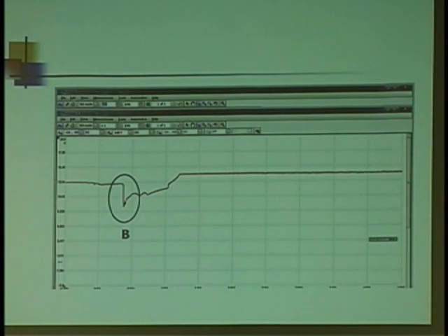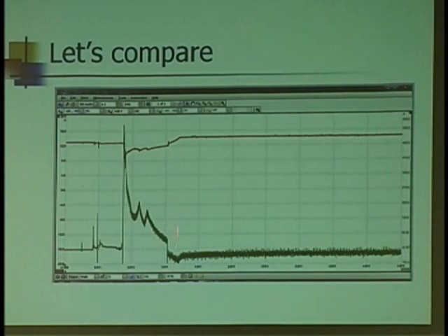Now on a VAT 40, you generally cranked about 200 amps or so. My starter just pulled about 500 or 600. Wow. And that's not an unusual number. I know that's not what we were taught to do when we did starter cranking draw tests. But this scope is measuring things happening in microseconds. And when I first send voltage to that starter, nothing's moving. And nothing wants to move. And it takes that much to get that ball rolling. So that's not an unusual number.